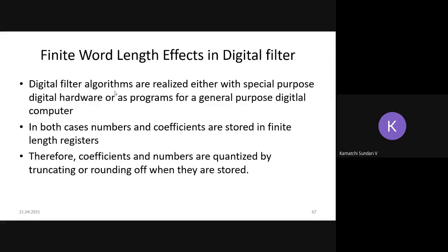In that case, I will have an error, isn't it? So the difference between the 20-bit data and the 16-bit data, whatever we can accommodate in my finite register, right? The difference between these two will register as an error in our calculation. So this is the concept behind the finite word length effect.